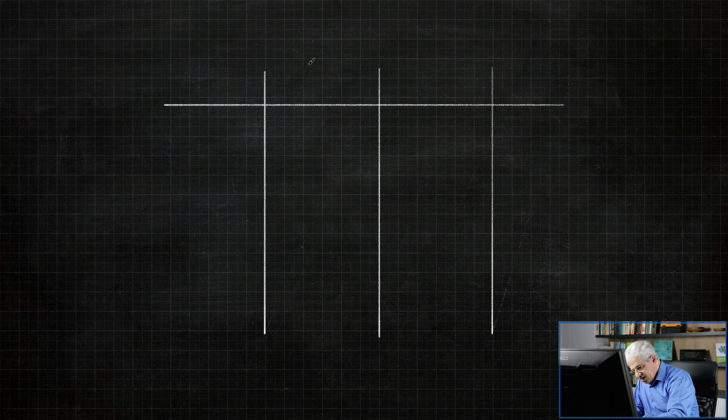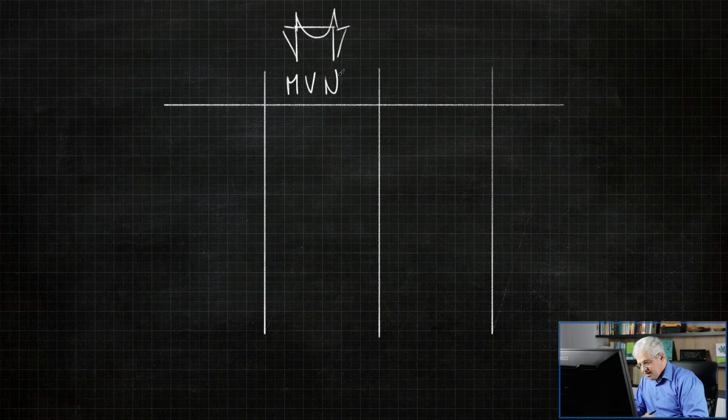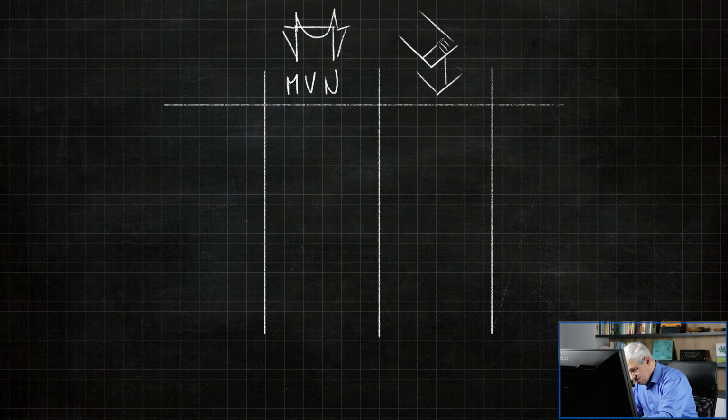We will start with a little bit of theory. Usually in SCIA Engineer for steel members, 1D objects or 1D elements are used. This is a line with some characteristics. I will show you some table. We have the calculation of internal forces, let's say something like bending moment. So we have bending moment, shear force, axial force. And then we have the steel checks according to Eurocode, calculation of stresses and stability calculation and whatever.